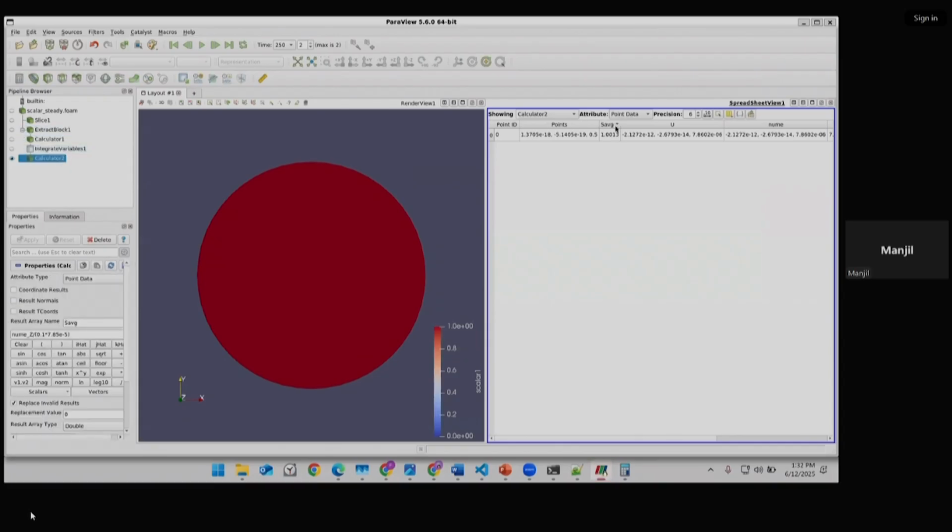So you can see in the calculator part, the S average should actually be 1, but we can see that there is a slightly greater value. It must actually be a slightly lower value, because it will asymptotically reach the average inlet concentration. So this might be due to the numerical diffusion and error in our simulations. This should be 0.99 and it will reach 1 asymptotically.